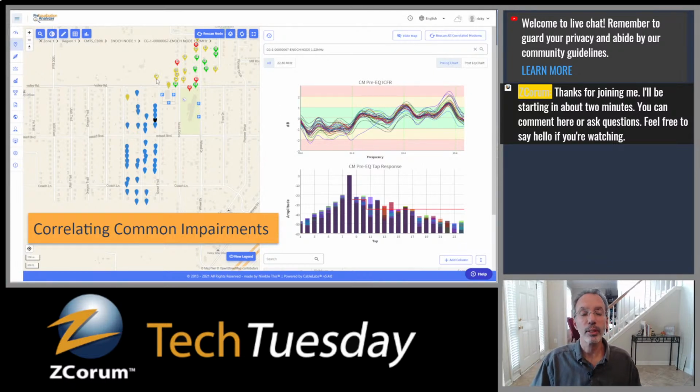So let's say that's the case. What I'm looking for when I'm looking at this map is the first good modem and the last bad modem. Or really, I guess it's the first bad modem and the last good modem, if you want to look at it that way. And then somewhere between those two things, I know I have a problem, right? Let's say this is my first bad modem, my last good modem. Somewhere in between here, I've got a problem.